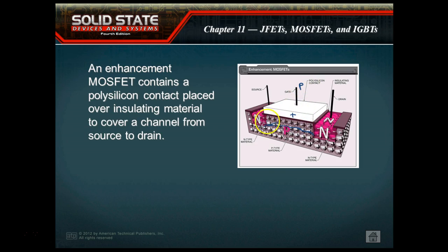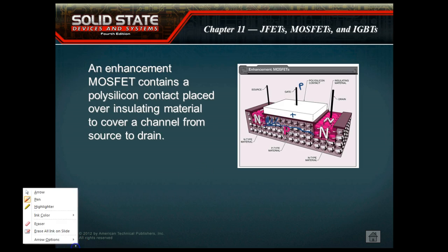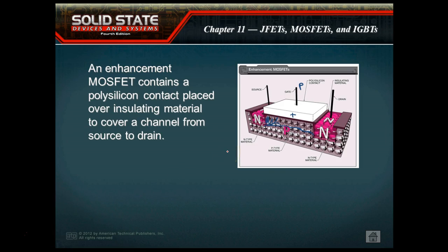As soon as I hit what we refer to as a threshold voltage, then we have a channel. Now we're not forward biasing this thing, but if it was a JFET, this would be forward biasing by putting a P on the P and an N on an N, right? You understand that? So we're not really calling this forward bias.